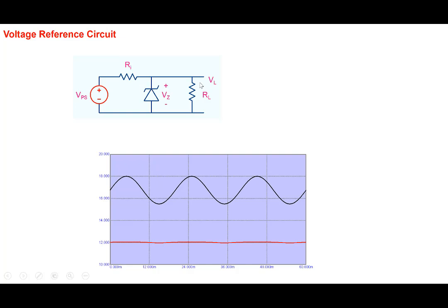And when we apply it to a properly designed circuit like this, the Zener diode will operate in the breakdown mode, and therefore the voltage across this particular element will be constant, and a constant voltage will appear across the RL here, equal to the Zener voltage. So this is what is shown here. Note that a Zener diode is not perfect. We also saw that the steep region is not completely vertical, but it has a little bit of resistance, and that's why you see some small changes, a little bit of ripple that is present here. Okay, so in a simple case, if we ignore the small resistance of the Zener diode, then this is how the circuit would look like, and then we would get a perfect output voltage here. And depending on the value that you require here, you can choose an appropriate Zener diode.